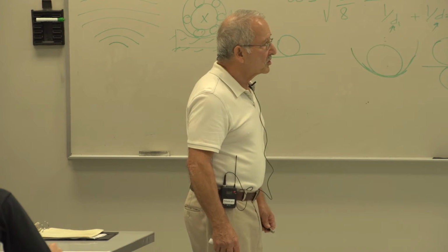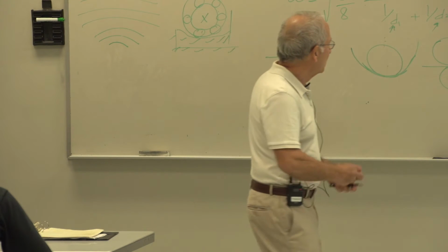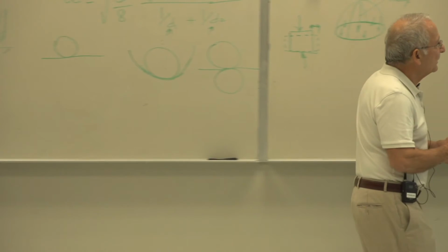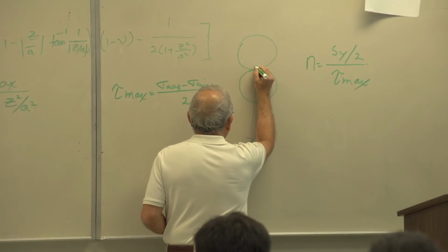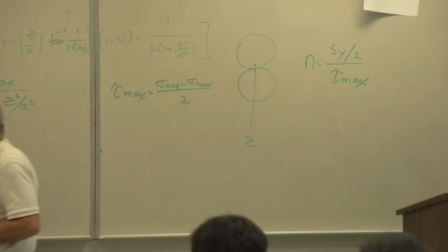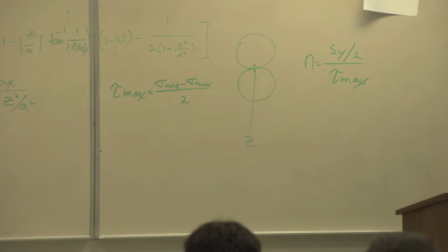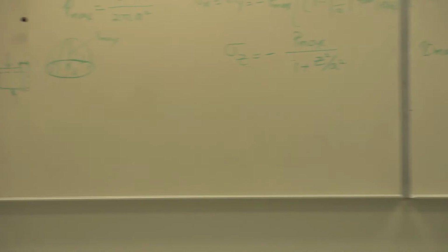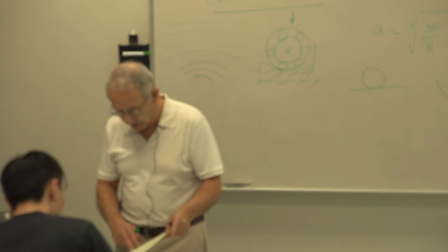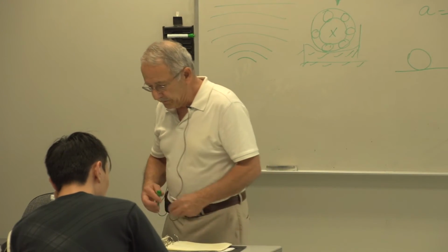This shear stress that occurs actually below the surface, so it occurs here or here, not right at the z equal to 0 mark, is the cause of a lot of failures, and we'll talk about those in a few minutes. But next, let's take a look at two cylinders in contact.